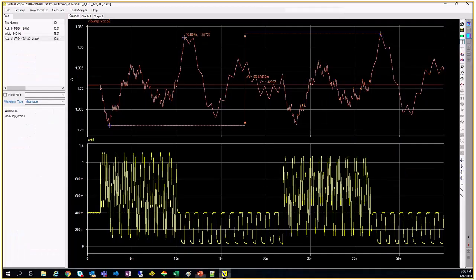You're starting at 1.35, you're pulling the current, you're suddenly sucking so much current, but you're not able to meet that voltage because it takes time, right? It's suddenly pulling 20 amps of current, right? It's suddenly pulling 1 amp, 2 amps. So there's a drop. This drop comes. So you want to reduce this drop as much as possible. You want to keep the voltage as stable as possible.